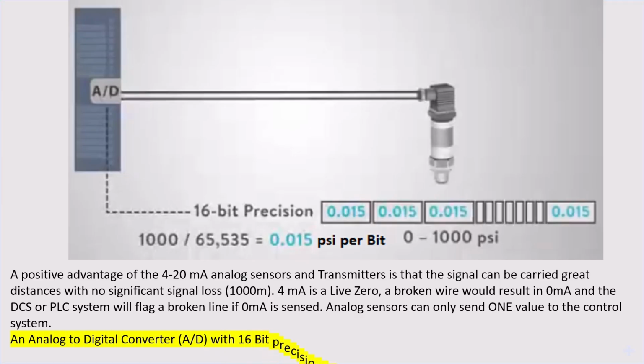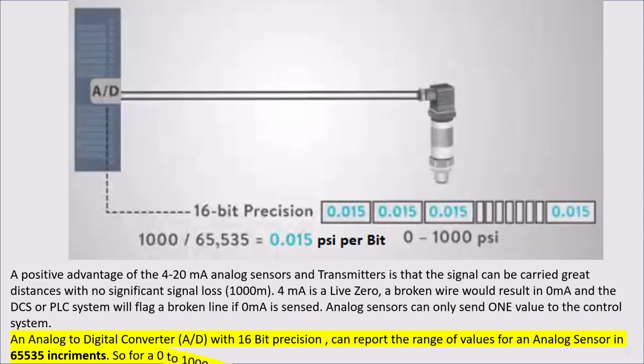Analog sensors can send only one value to the control system. An analog to digital converter, A to D, with 16-bit precision can report the range of values for an analog sensor in 65,535 increments. So, for a 0 to 1000 psi transmitter, each bit represents a change of 0.015 psi.